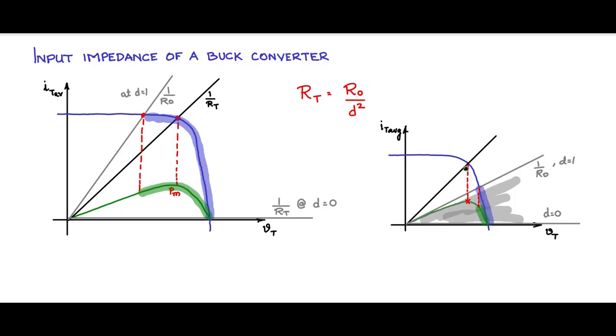And therefore this scenario would lead to a situation where the buck converter operation is not meaningful. Whatever may be the duty cycle, the control input, the buck converter will not provide a load line which will give a peak power operating point.